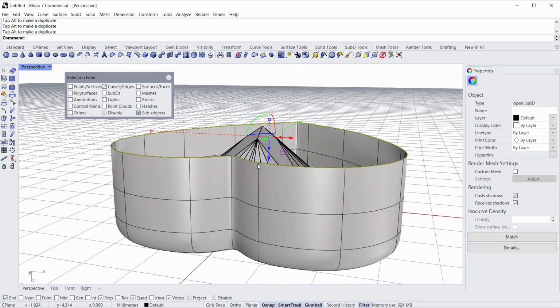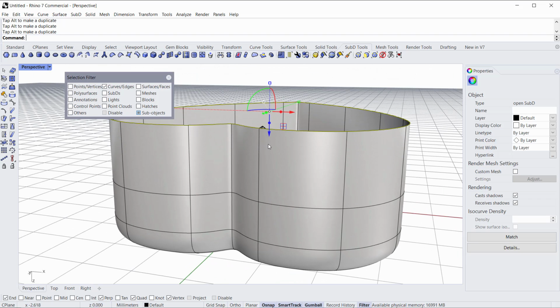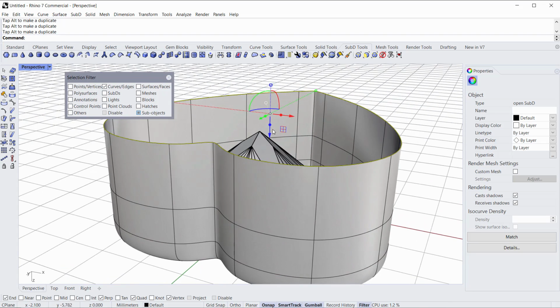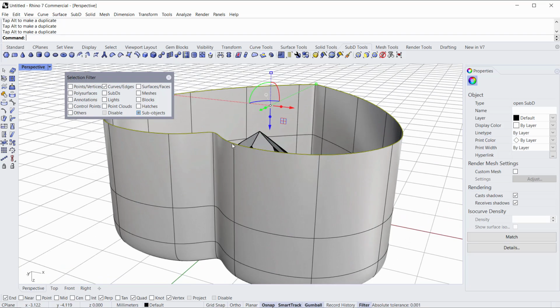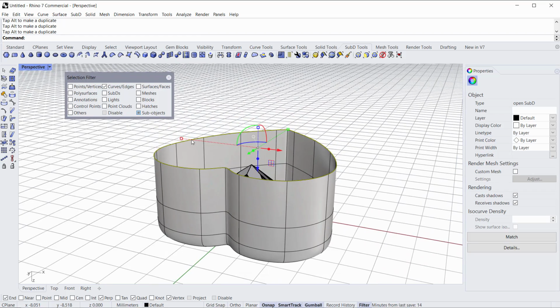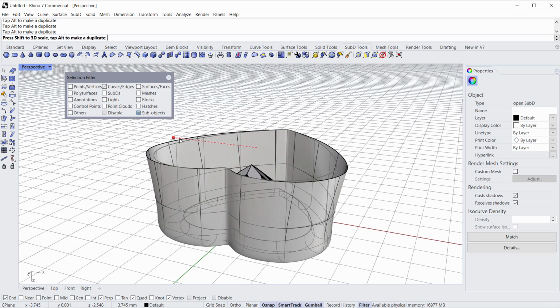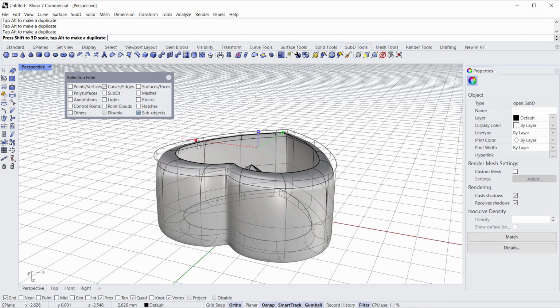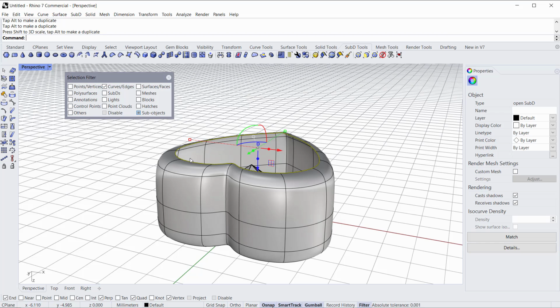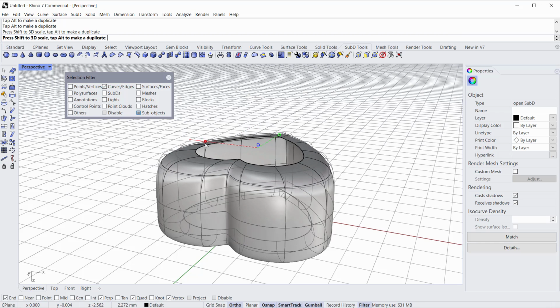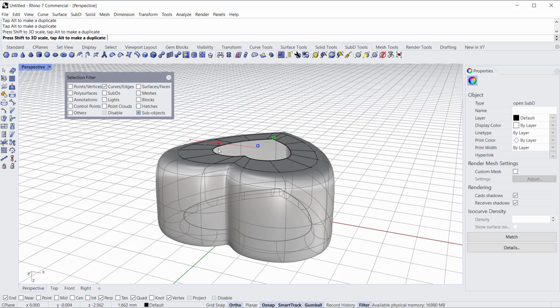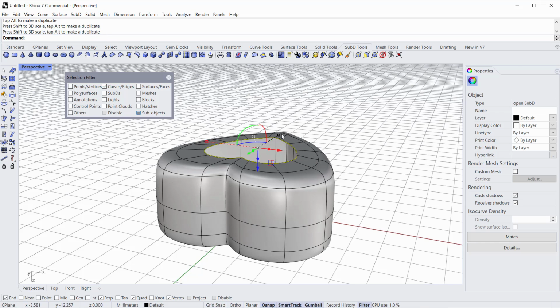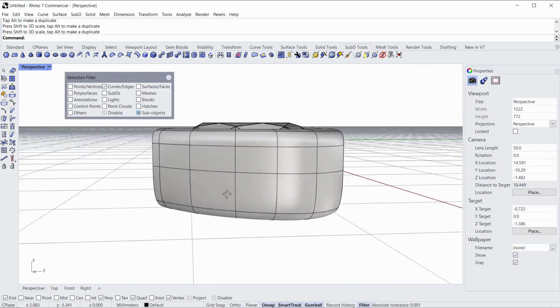I'll then spin the thing over a little bit and maybe just grab the arrow. So instead of adding another row, maybe I'll just pull on it and move that row down a little bit. I'm going to do the same thing that I did earlier to make the top lip of the bezel, but on the bottom. So I'll grab this axis. I'll hold Shift to get them both going here, and then I'll add Control to the mix and get a set of faces. Now I want to do this again. So with that still selected, grab Shift, Control, and get another loop of faces here or another edge added. All right, so there's the bottom.